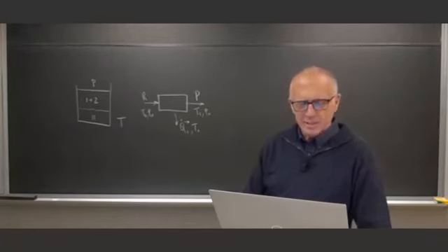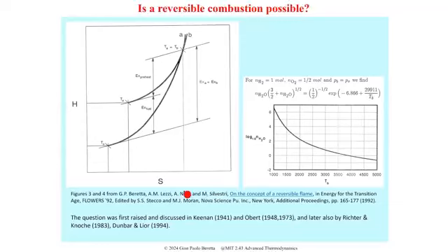So we ourselves worked on some calculation, you can go to this reference, and we computed the amount of water that you have to dissolve. This was a combustion of hydrogen, and we wanted to look at what dilution you should put in, to dilute your products of combustion, which in this case is just water, in order for the temperature at which they touch not to be too high.